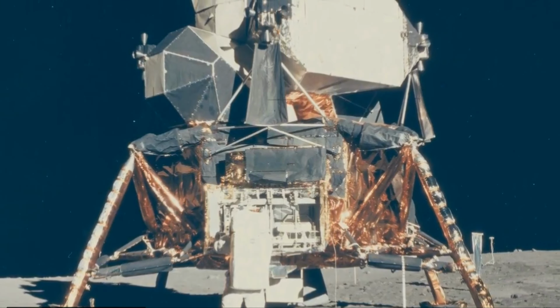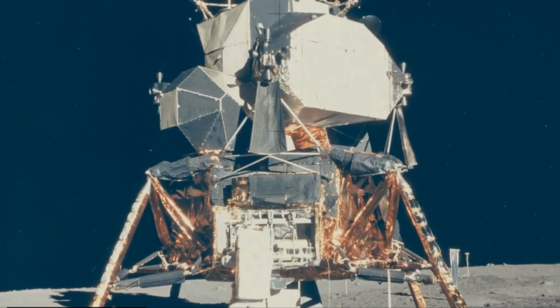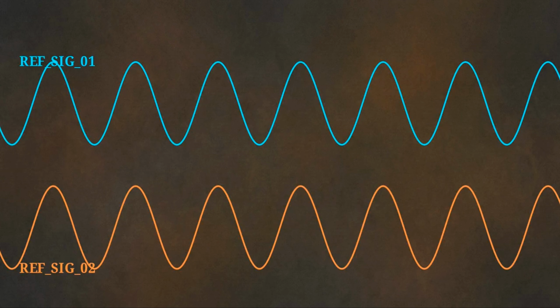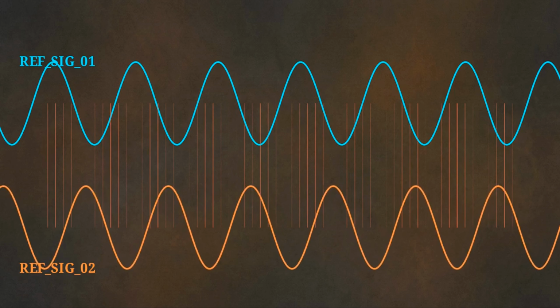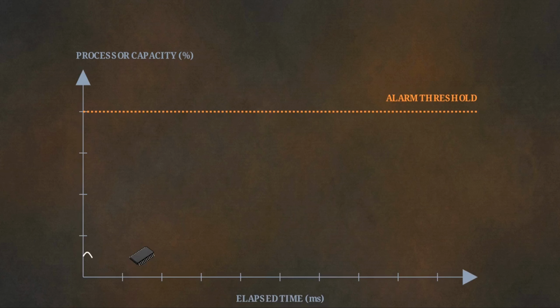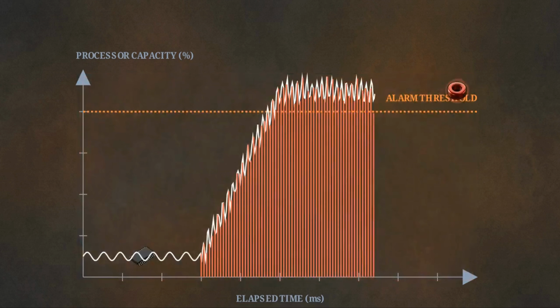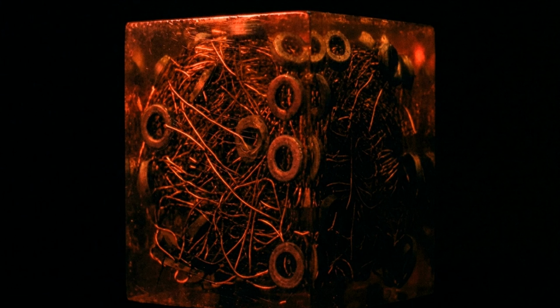During the Apollo 11 lunar descent, this hardware faced a catastrophic system stress test. A rendezvous radar switch was inadvertently left in the wrong position. This caused a hardware mismatch between 15-volt and 28-volt reference signals. The resulting phase drift generated approximately 6,400 spurious hardware interrupts per second, starving the computer's processor and triggering the infamous 1202 program alarm. The physical entombment of the code saved the mission.